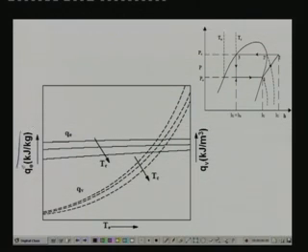As you can see, it has unit of kilojoule per kg, and QV is the volumic refrigeration effect, that means refrigeration effect per meter cube of refrigerant flow. On the x axis I have evaporator temperature, and I have these performance parameters for different values of condenser temperature. Condenser temperature is increasing in this direction for specific refrigeration effect, and again in the same direction for volumic refrigeration effect.